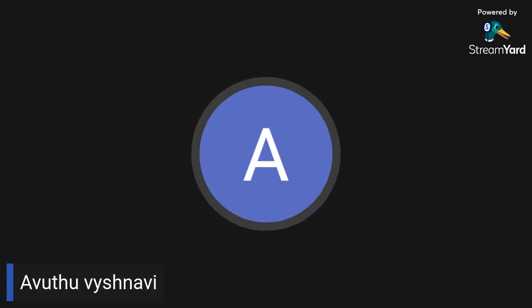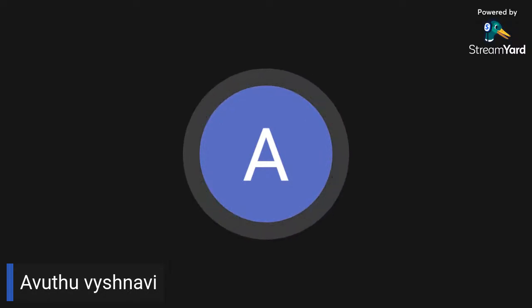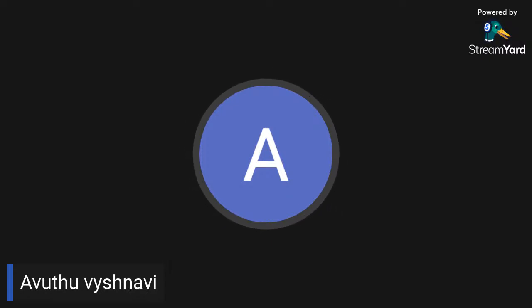access general things like new design, new electronics, all these new drawings, next the save button, and so on. This is known as the user profile, and this is the help access bar. To save the file, you can also type Control plus S, and I'll type Fusion. I can save this in the location of project one, which I just created. So save. Here we see Fusion v0, which indicates version 0, the first version.